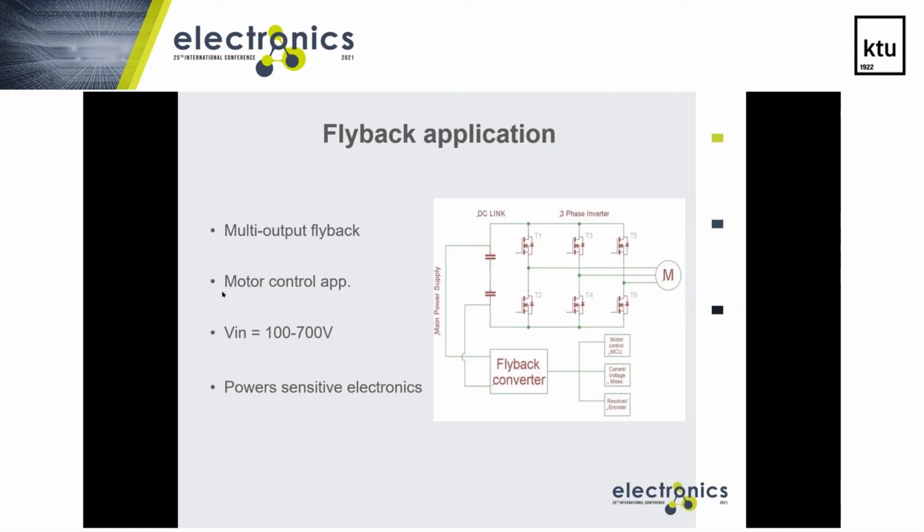All PWM converters have non-ideal parasitics that lead to ringing waveforms that must be properly suppressed. Without this, semiconductors can be prone to failure and noise levels will be higher than necessary. In this article, we will talk about the practical design techniques for the most commonly used snubber and clamp circuits for the flyback converter. So the article focuses on the practical and efficient design of snubbers in flyback converter topologies.